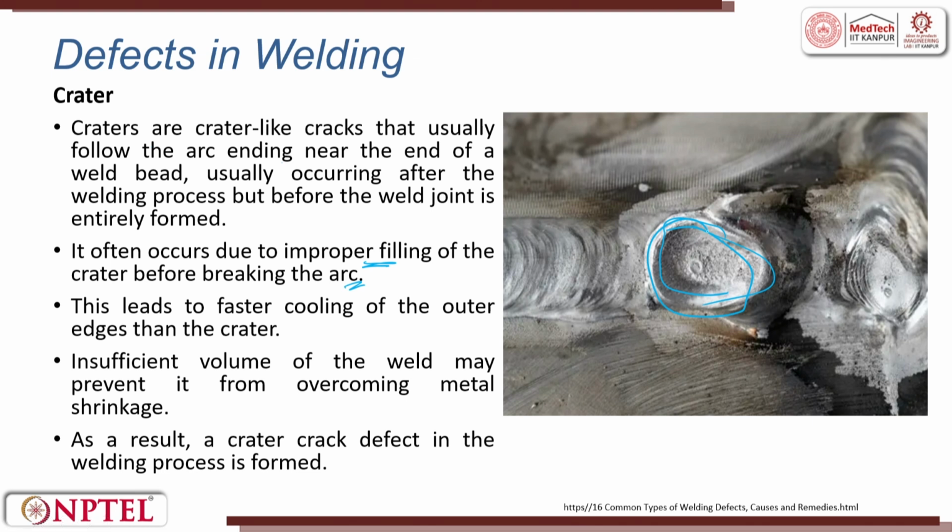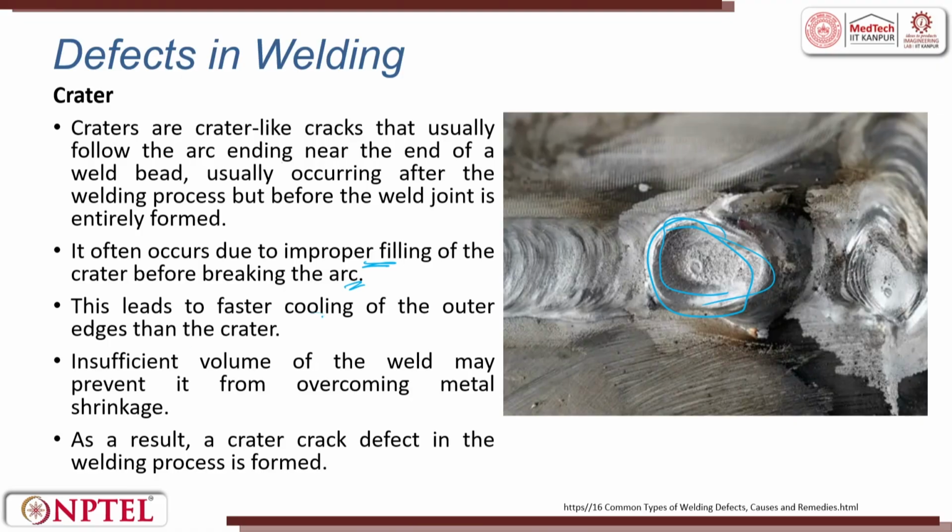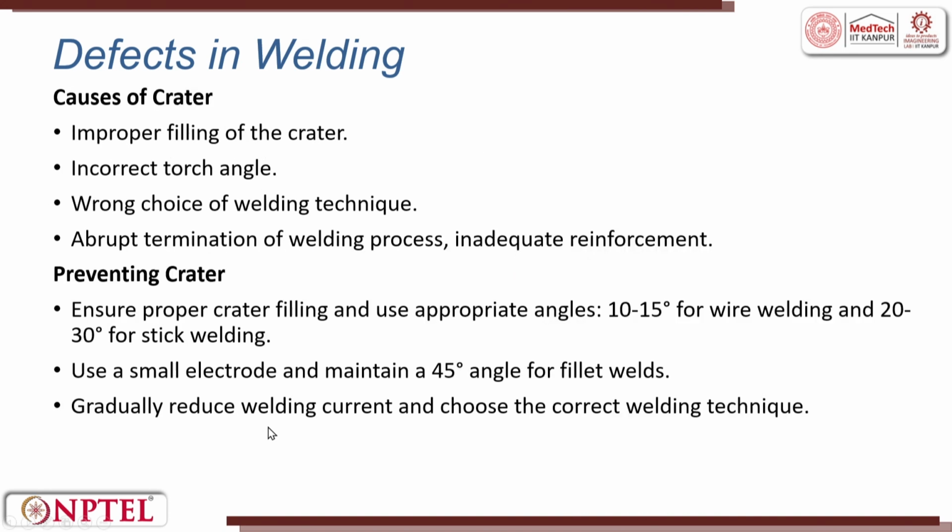Basically, why does it happen? There is a solidification phenomenon happening. When solidification happens, the liquid tries to move, right? Once it tries to move, there has to be enough material to fill up. If there is not enough material, it creates a crater. This leads to faster cooling at the outer edge than at the crater. So insufficient volume of the weld may prevent proper filling, resulting in crater crack formation. So ensure proper filling, and you should also try to maintain the welding angle, the stick angle and other things.